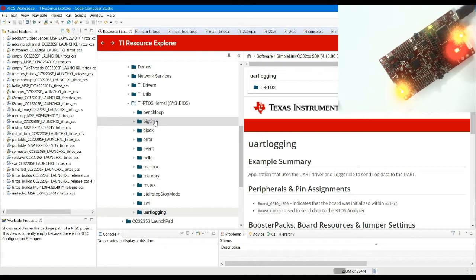You can actually see how much time has been consumed by one particular task and how much time was given to the idle, and if you had implemented threads in separate priorities which preempt each other, you can have a graphical overview of how much time has been given to which thread. For that we need to enable something called logging.